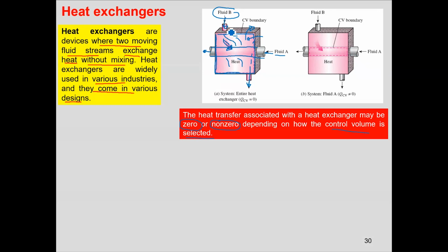This heat transfer, which is from fluid B to fluid A, is within the control volume. Since it is not crossing the control volume boundary, you would consider this as a case where your control volume has zero heat transfer.